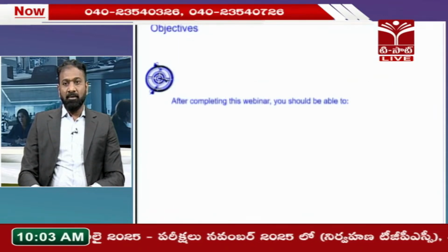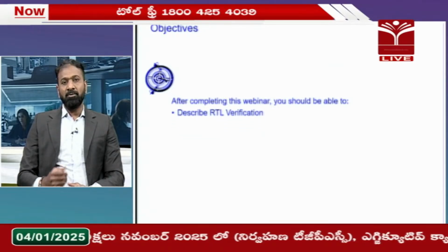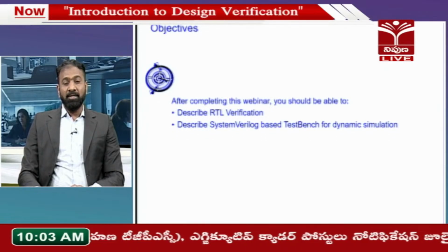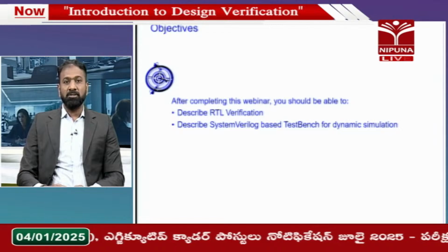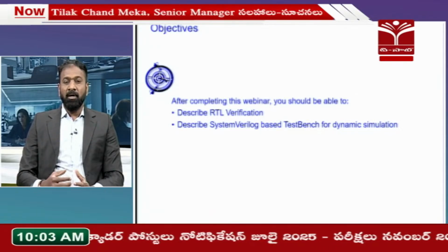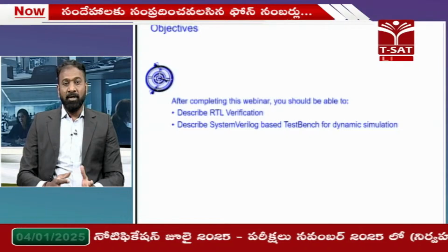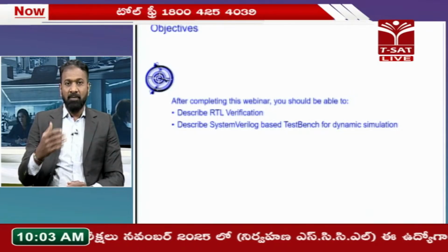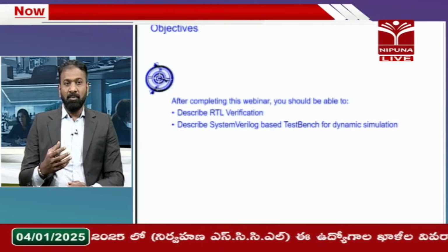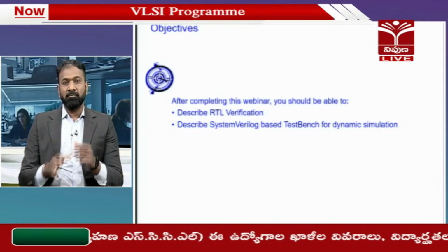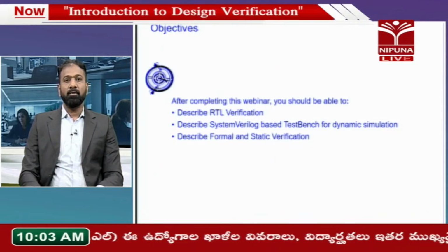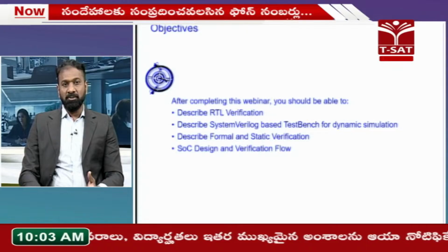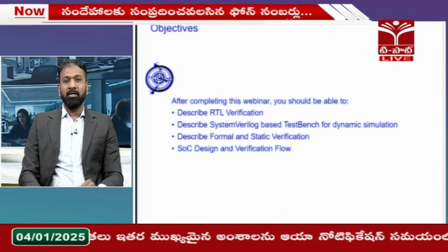The objectives of this webinar: once this webinar is done, you should be able to describe what RTL verification is. You should be able to use a SystemVerilog based test bench for dynamic simulation. Typically, we are all aware of some of the HDLs like Verilog, VHDL. Here in this session, I am going to introduce you to the SystemVerilog language, its high level constructs, and I will also show what kind of test bench architecture this SystemVerilog based test bench has. And then we look at formal and static verification, and you should be able to explain what an SoC, the system on chip, is, and the corresponding design and verification flow.